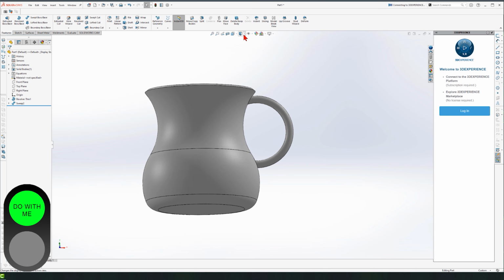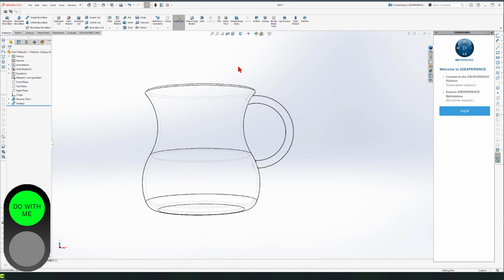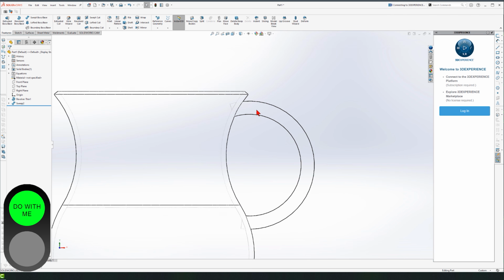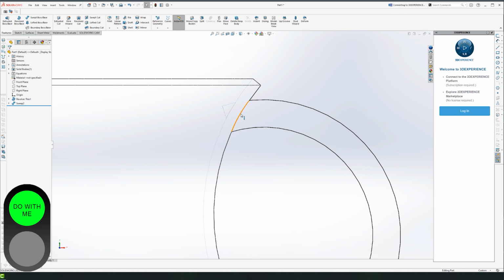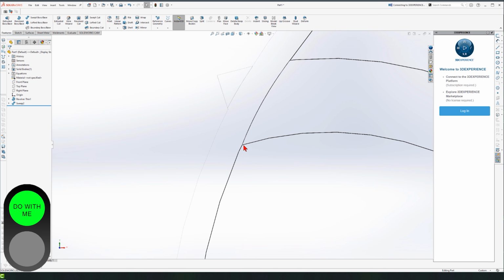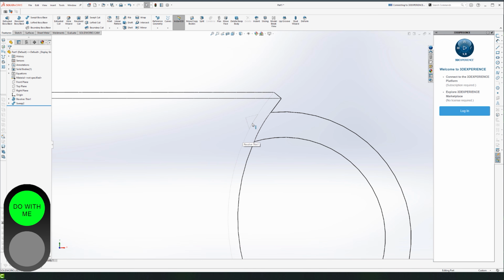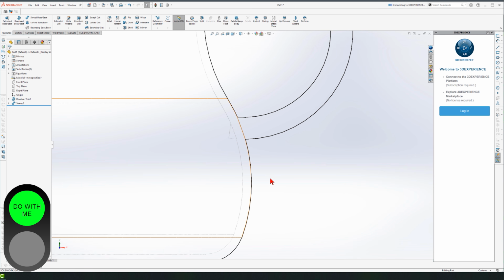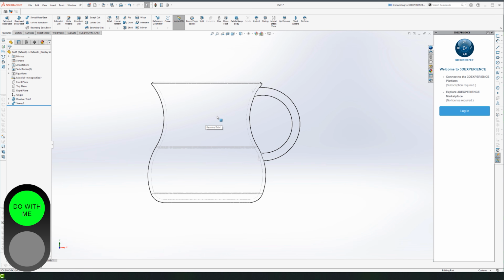And the way I do this is to change my view by clicking here to show the dash lines, press the spacebar, and Normal To. Now, if I push my profile a little bit out, it might solve the issue, but I might create another issue by creating an opening here. So I have to clean these sharp points that are sticking into the can. Now, there are some advanced ways using surface modeling, which is a little bit overwhelming for you at this point to do this. So I'll try to do it in a harder way, but using simpler tools.